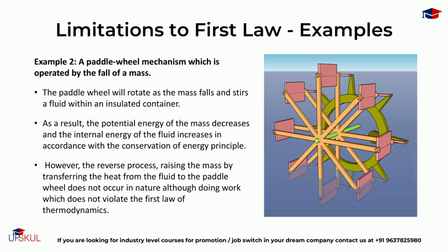Next, let us consider a paddle wheel mechanism which is operated by the fall of a mass. The paddle wheel will rotate as the mass falls and stirs a fluid within an insulated container. As a result, the potential energy of the mass decreases and the internal energy of the fluid increases in accordance with the conservation of energy principle.